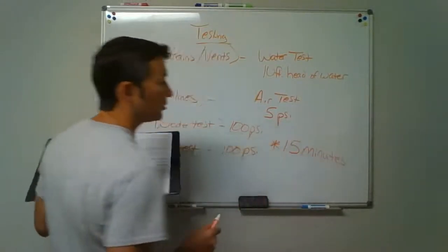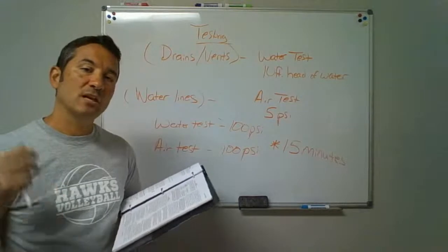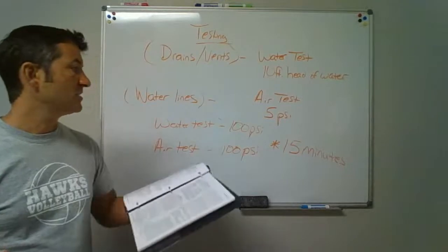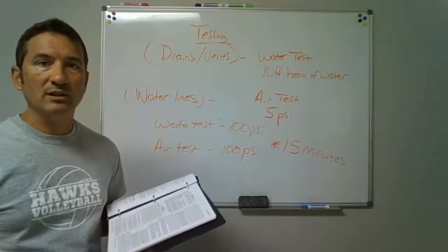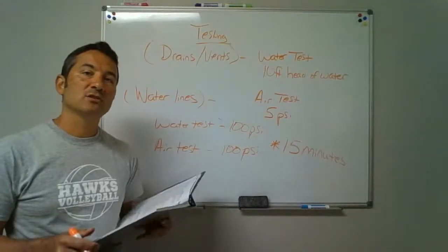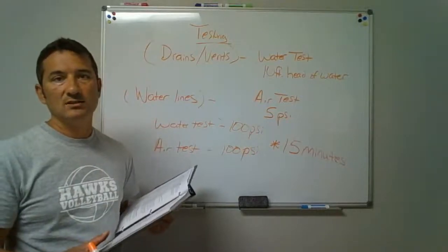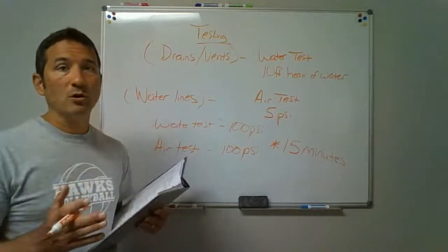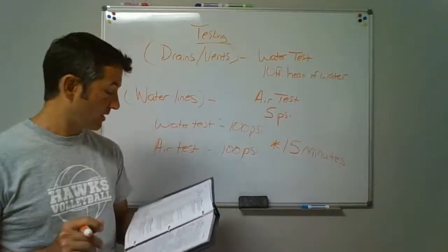Now you say, oh, it just holds for 15 minutes. That's all it's got to hold for and let it off. No. Well, we've got to have it on pressure for 15 minutes before the inspector shows up. He wants to see it holding. It should hold for however long you put the test. Water should never leak out of it, okay? But we've got to have the test on for 15 minutes. The inspector doesn't want us just to say, well, wait just a second, hang on. We top it off real quick and say, quickly look at it. You don't see any leaks, okay, and then we just let it back off. Sometimes if you got a small leak, it might take a little while for water to start showing up. He wants to make sure it's been on for at least 15 minutes. If you got a leak, it's going to have showed up by then. Okay.